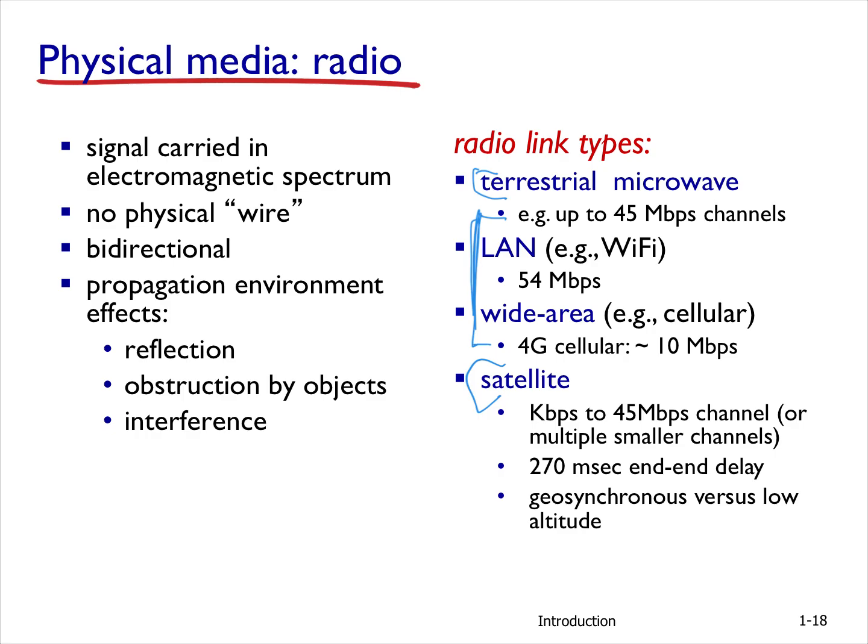Whenever you don't want really to dig the ground and pay a lot of money to the infrastructure, and you want to connect 2 remote points together, the alternative to cable connection, if you don't have it, is the microwave link. It's a wireless connection, but it's only meant to come from one fixed point to another fixed point across tens to hundreds of kilometers. So it can reach a couple of hundreds of kilometers.